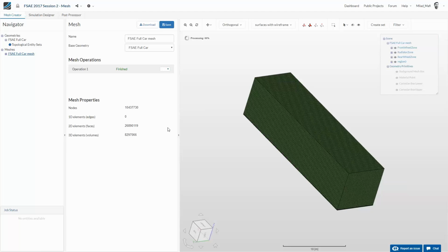Some people are asking questions like, why is the refinement at this part finer and for this part more coarse? What we did is we started with a simulation which was very, very fine, and then decreased the refinements until we saw that the results started to change. And from our experience, this kind of setup is the minimum viable setup if you do Formula Student aerodynamic simulation with SimScale, but for sure later you are free to modify the settings. But don't forget one thing, just having a large model is not making a simulation good.